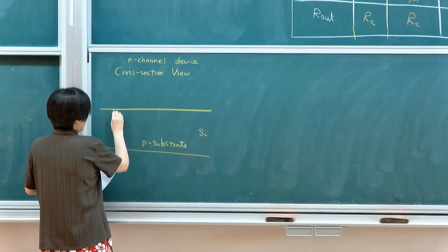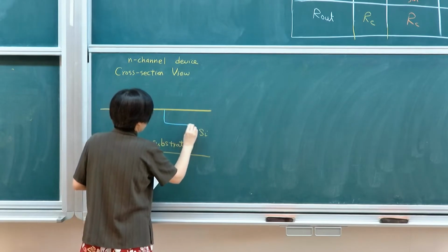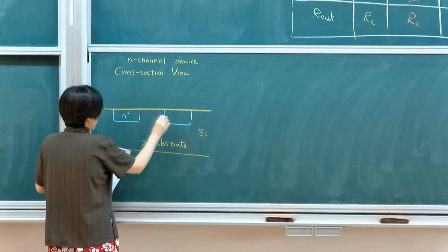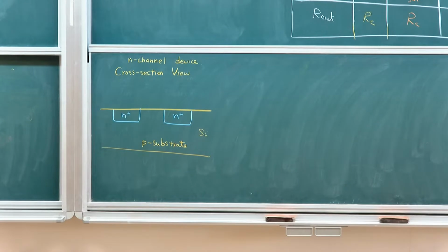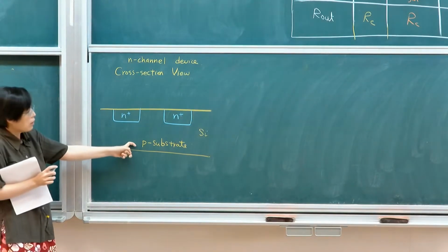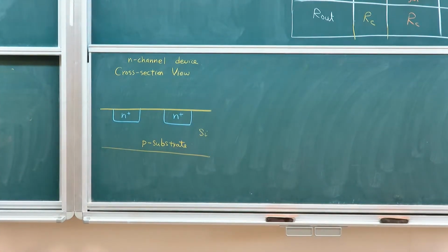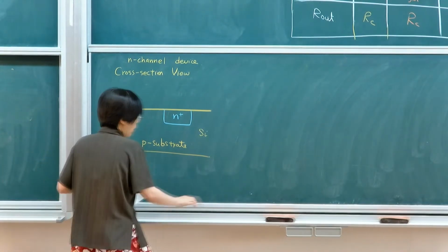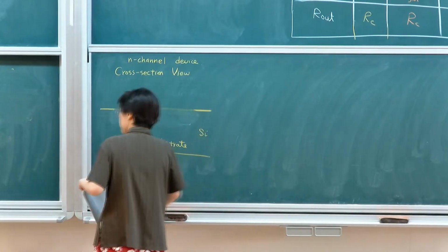If you look at the bottom structure of the device, it will be something more like this. For the silicon part, I'm constructing a device which is not connecting at the beginning. So I'm forming an N+ version under the silicon P-type substrate. So this is P, and you construct two connecting terminals with N+.